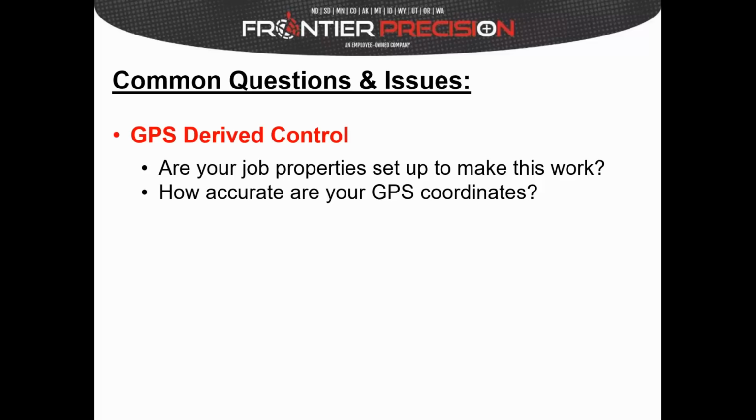Okay, so it's pretty counterintuitive to use a total station because it's more accurate, but then base all those measurements off of inaccurate GPS coordinates. We see that happen once in a while. You need to make sure that you know before you start with your total station that your GPS coordinates are accurate. It's the only way your total station shots will also be accurate if you're basing them off of that information.